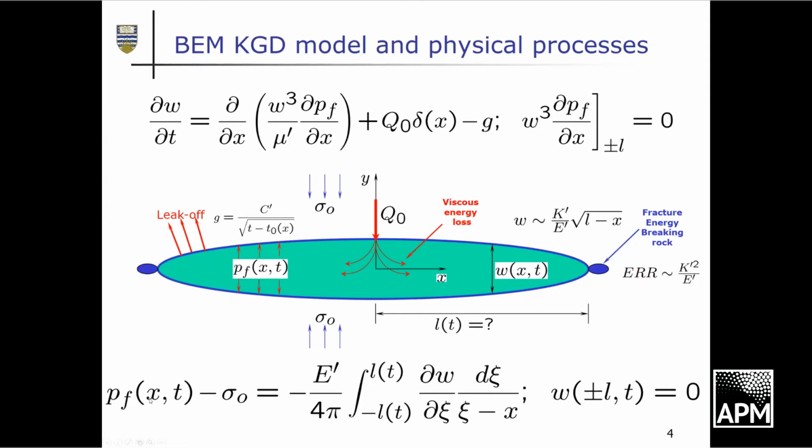And that's a statement of balance of mass within the fluid within the fracture. And this is a statement of equilibrium. So the forces on the boundary of the crack minus the geological stresses relate to the fracture opening through the elastic modulus. So this is a singular integral equation. And we have these boundary conditions. One of the big problems is it's a free boundary problem, so we don't know where the boundary is.